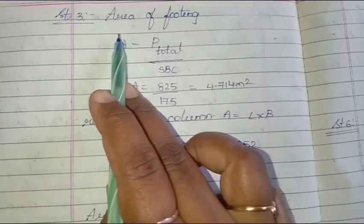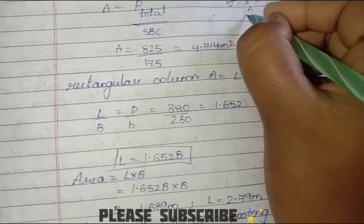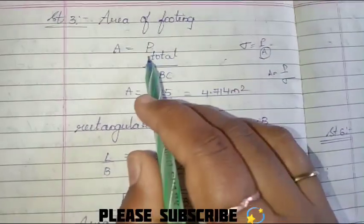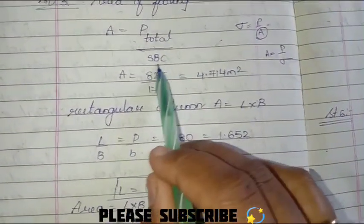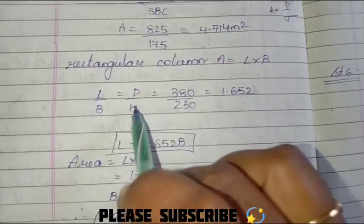So step 3 is going to be the area of footing. As I already told you, stress is equals to force by area. Now we need area. Area is going to be P by stress. P is nothing but the total load which we have calculated in step 2, and safe bearing capacity is given in the question already. So that's going to be the area, and we have to be designing it.